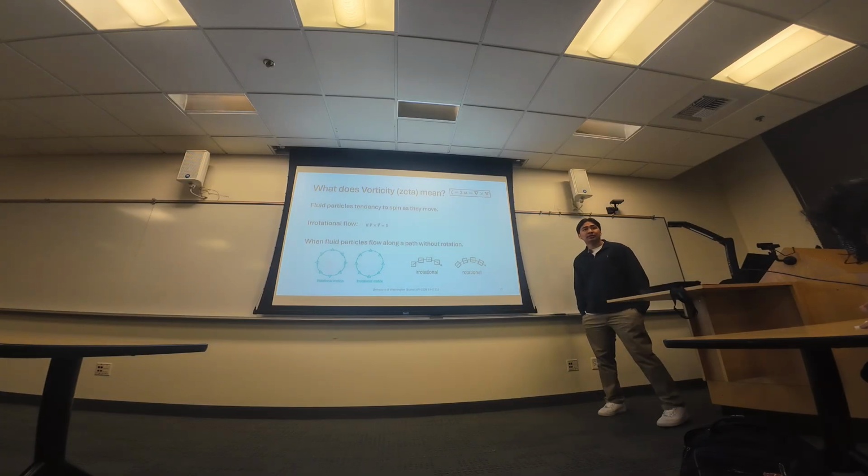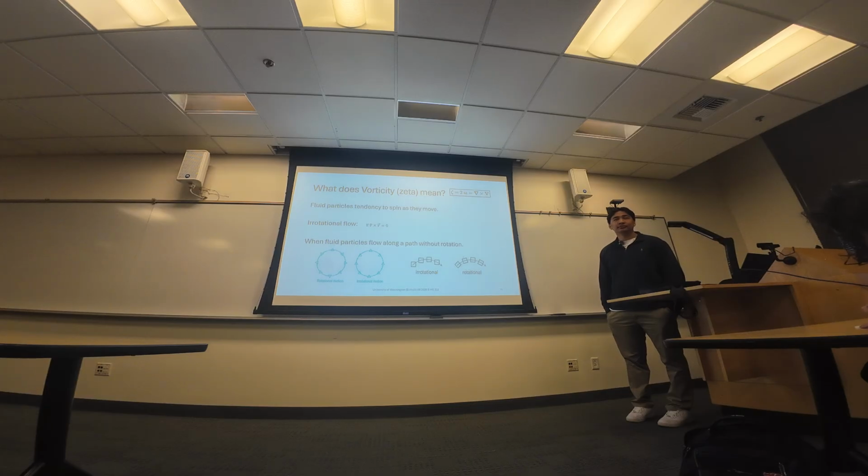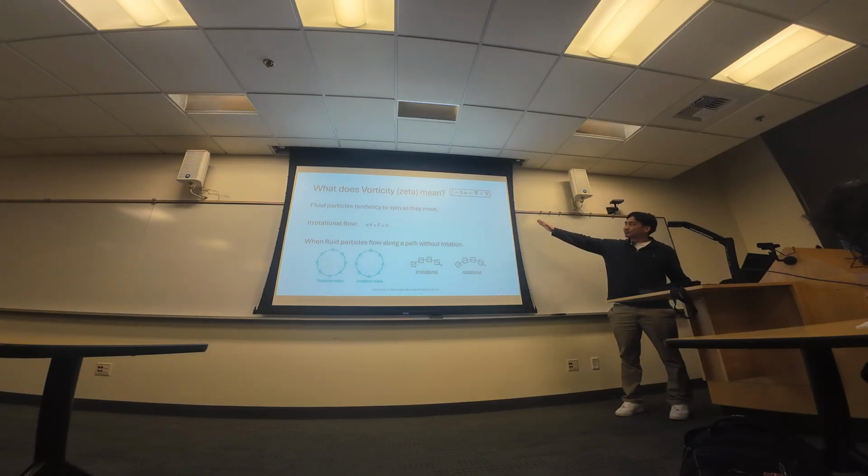Yes? So vorticity is the measure of how much is irrotational? The term irrotational is when that equals 0. So it's not really the idea of how close it is to 0, if that's what you're asking. Okay, so it's more like the measure of how rotational it is. Yeah, basically. It's a good way of thinking about it, because if it's 2 omega, there's only one variable in there. So the higher your omega, the higher the angular velocity. So you can think of vorticity as how high my angular velocity is. That answers your question.